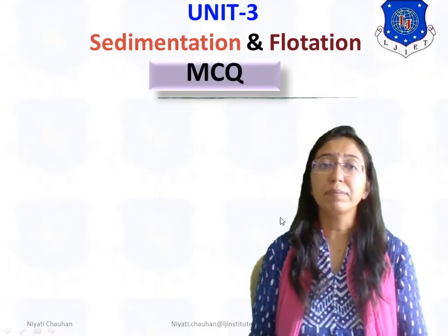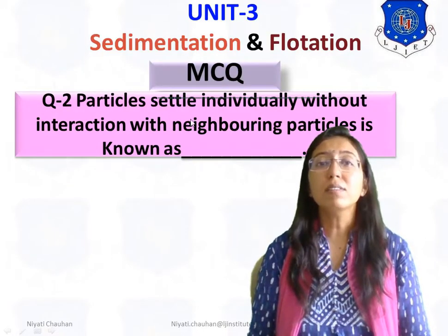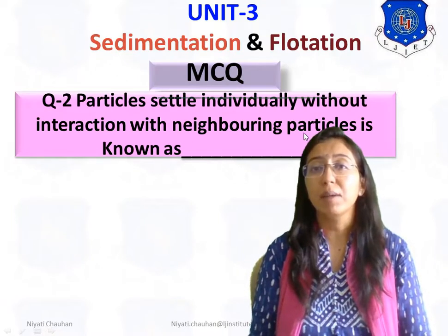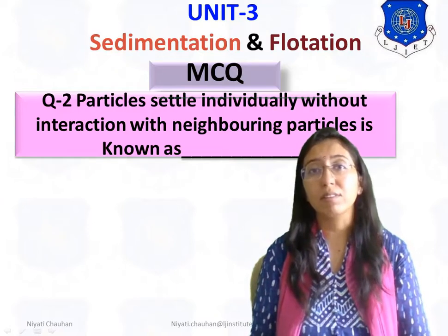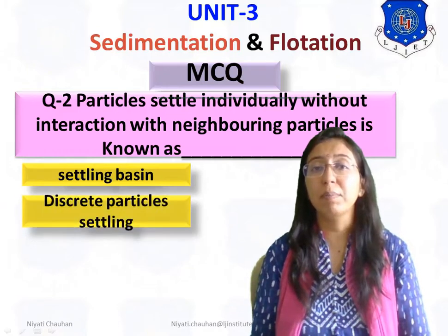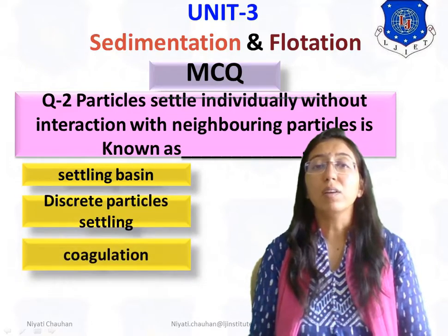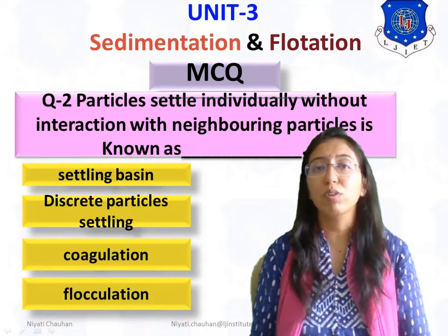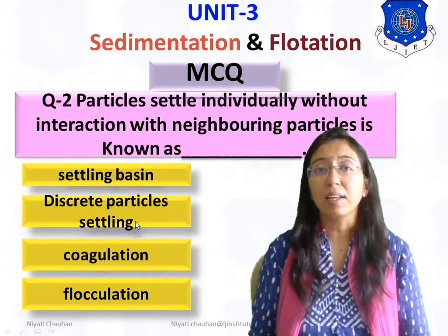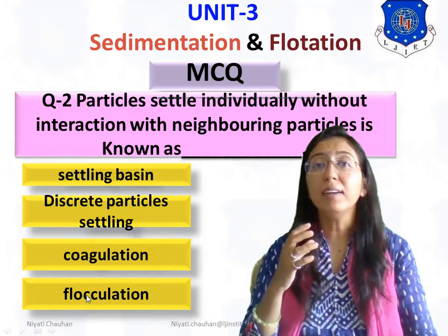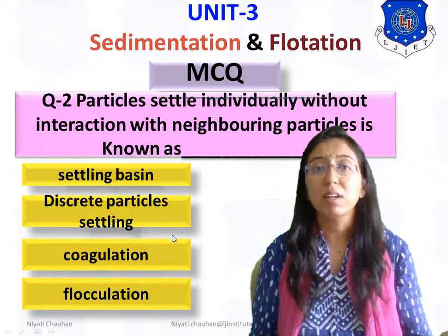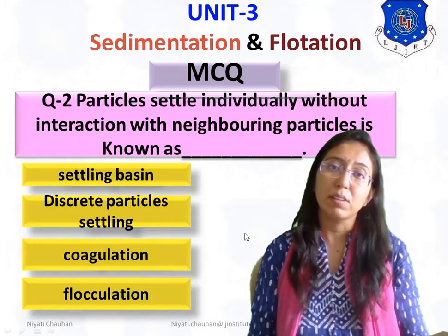Next question: particles settle individually without interaction with neighboring particles is known as: number 1, settling basin; then discrete particle settling; then coagulation; and flocculation. In discrete particle settling, there is no interaction with other particles. So the answer is discrete particle settling.